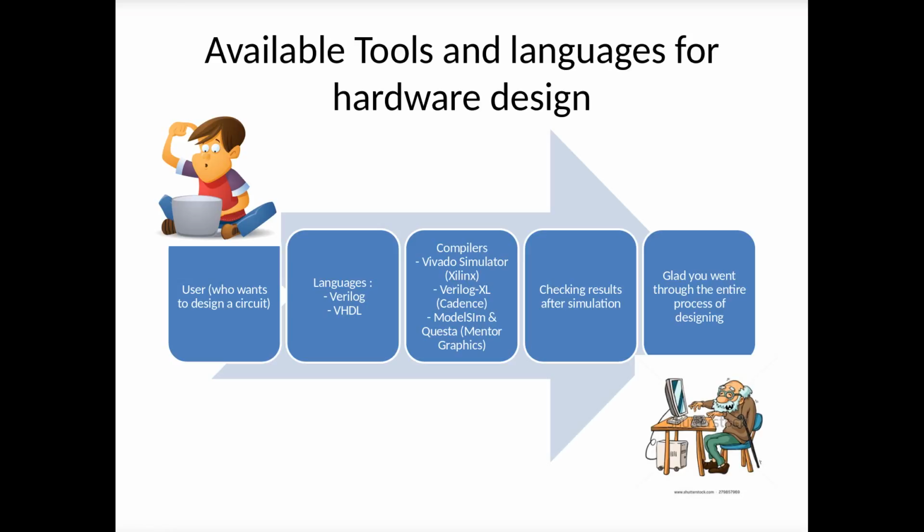So what are the tools that a user has to use before he can implement the design? So suppose we are the user who has an idea. This is converted to a machine readable code using hardware description languages known as Verilog and VHDL. This is also used to create something known as a test bench that is used to test your design against various inputs.